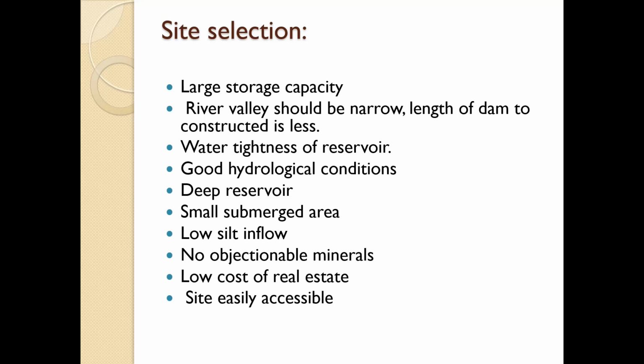And when acquiring the land also, we need to take care of all these things. Still we can see there are so many problems of people displaced by the construction of dams, and the site should be easily accessible. So these are the site selection criteria for the reservoirs. This is all for the reservoirs.